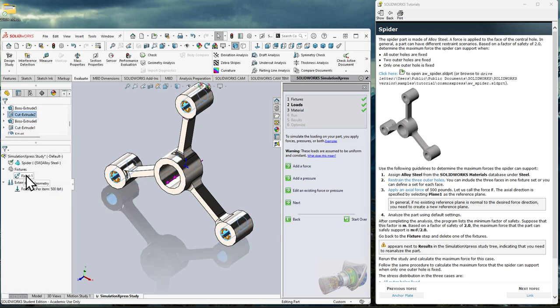So one of the biggest mistakes students make, I probably should have mentioned this earlier, is they'll add... So I have all 3 defined in one fixture, and I'm going to edit this fixture, but sometimes students will replicate these, so they fix the same point like 3 times, and it totally messes up your calculation. Or same thing, if you add a force there, and then you go and add another force there, and another force there, it's really like tripling it.